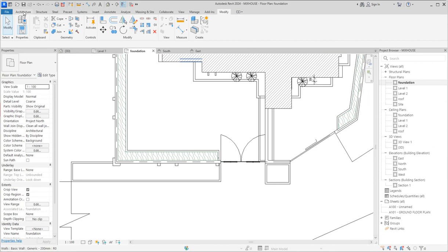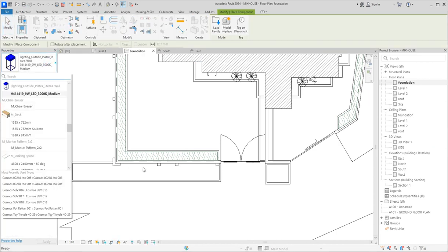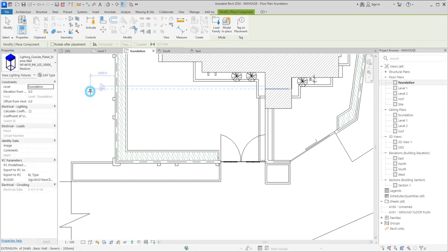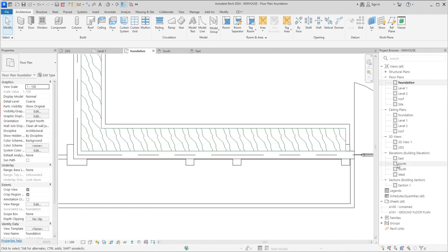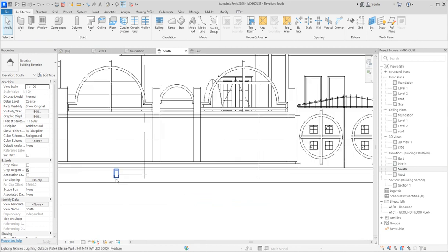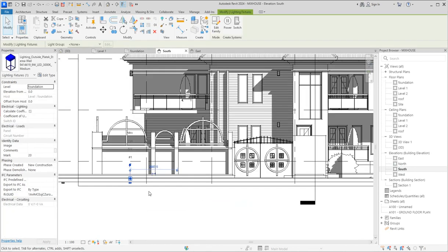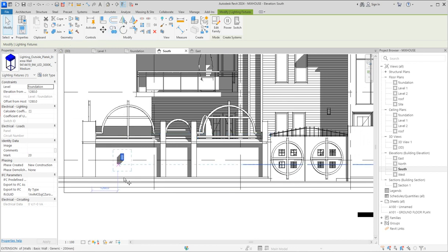In the foundation, select the lighting outside, exterior lighting that we did that time. Yes, good. So this particular light is what I need. So bring it here, place it around the wall. So what you do here, since it's the plain part, you don't need much. Just focus on this elevation. It's there already at the ground level. So adjust it and push it up. At this larger one, I'm going to make it 2. In the smaller space, I'm going to make it 1.